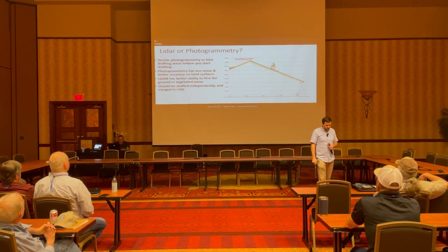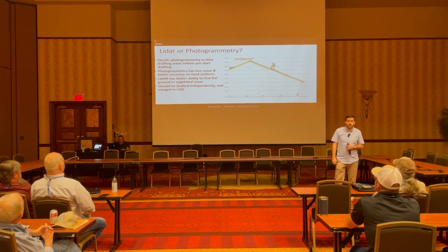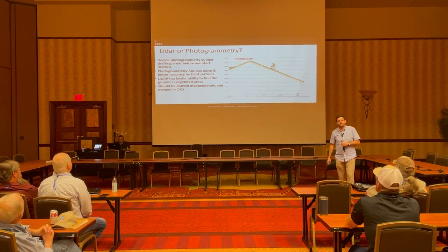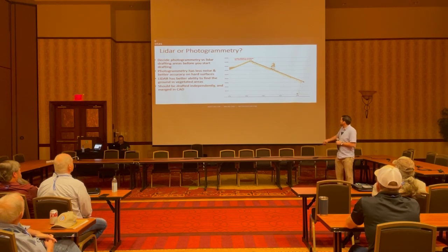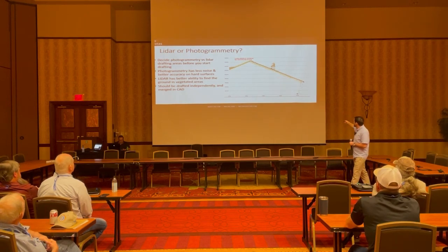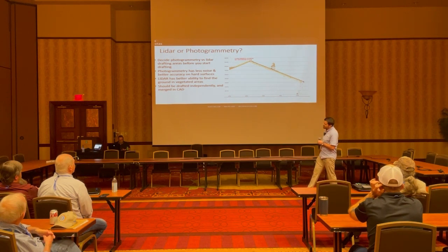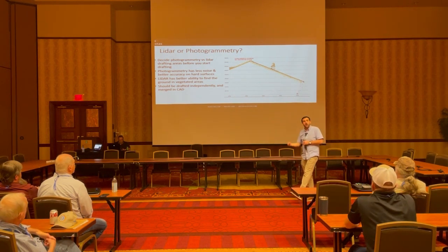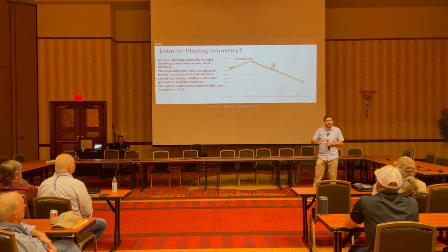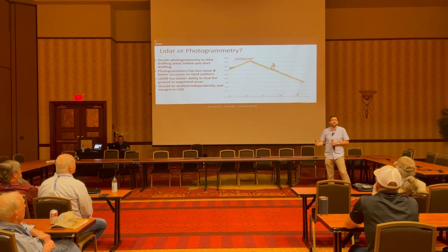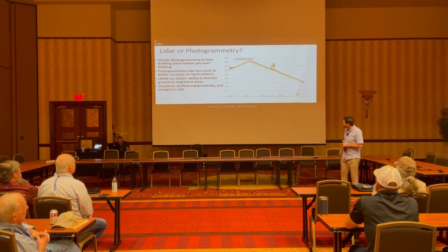One of the first questions when you're doing LiDAR line work drafting, if you have flown a site with a dual photogrammetry LiDAR drone, which again we like, is picking which one you should use. This shows some of the spread: on hardscape, that darker line is going to be photogrammetrically derived, and the yellow dots are going to be LiDAR derived. Photogrammetry remains more accurate on hardscape than LiDAR for aerial LiDAR.